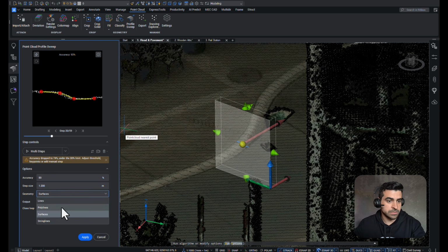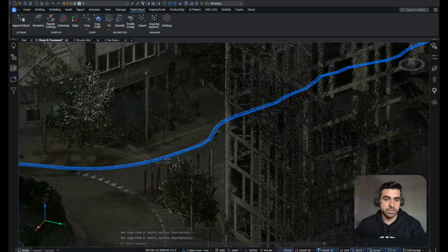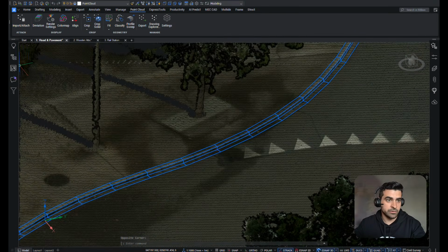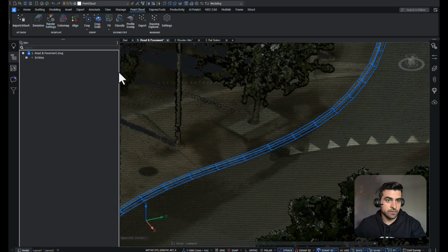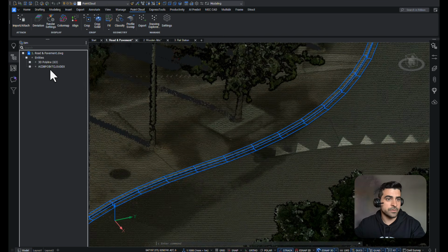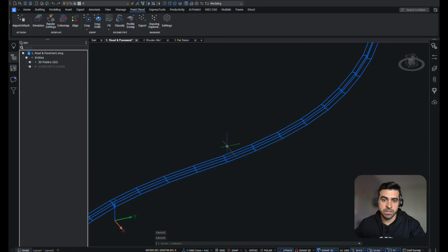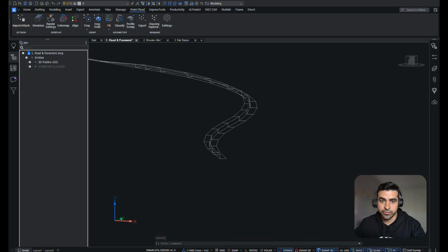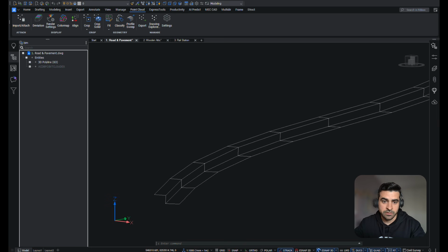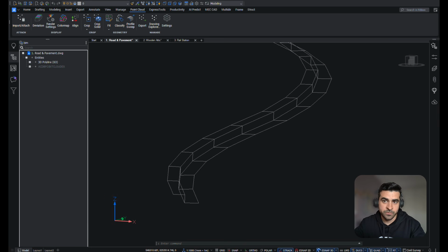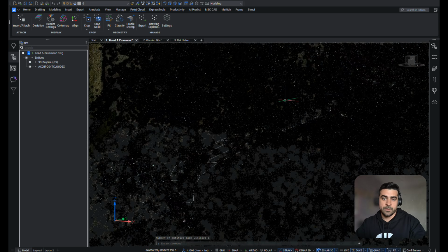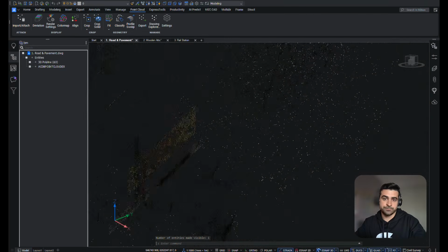geometry. Okay, let's leave it at polylines, keep both, and after hitting apply, we can see the result clearly. Okay, let's enable the structure browser and hide the point cloud. Right click to hide the point cloud, and we have 63 polylines in the drawing that represent the break lines and the profile lines of the pavement. So this would be one of the workflows in the surveying industry.